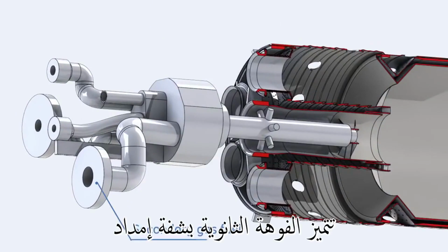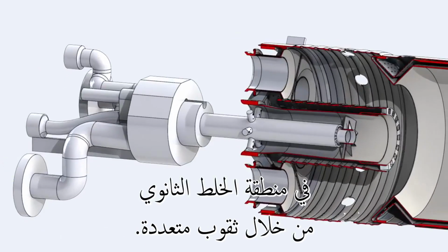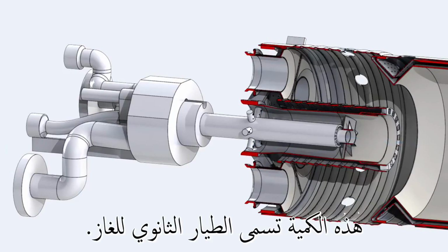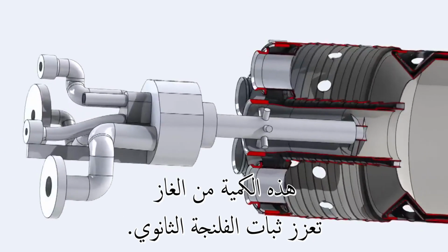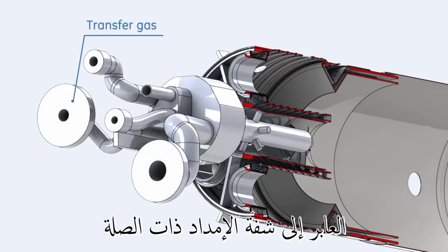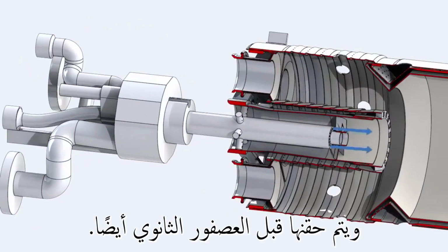The secondary nozzle features a supply flange for secondary gas fuel, which is injected into the secondary premix zone through multiple holes. A small amount of the secondary gas is injected after the secondary swirler. This amount is called the secondary gas subpilot. This gas promotes the secondary flame stability. Transfer gas for transient transfer operation is supplied to the relevant supply flange and is injected before the secondary swirler also.